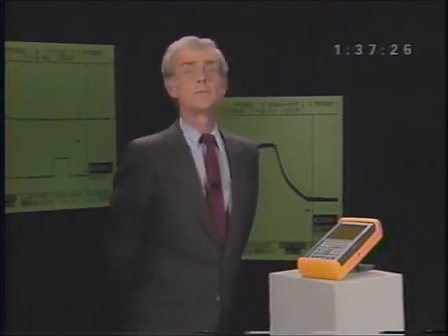The setup for this exercise will be useful in the shop for diagnostic procedures. Save it to Setup Memory 10. You're only saving the fast sweep setup. You may have to adjust the time base later to perform a slow sweep test.